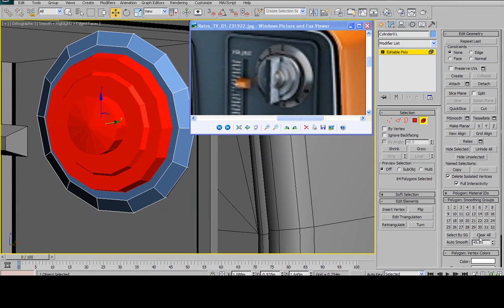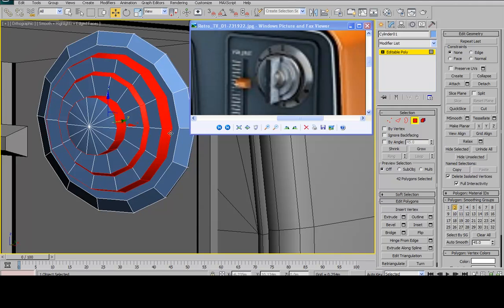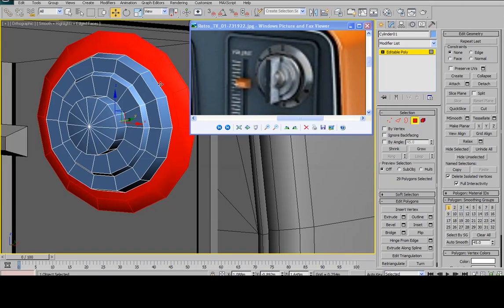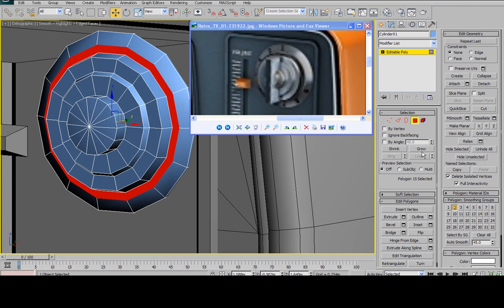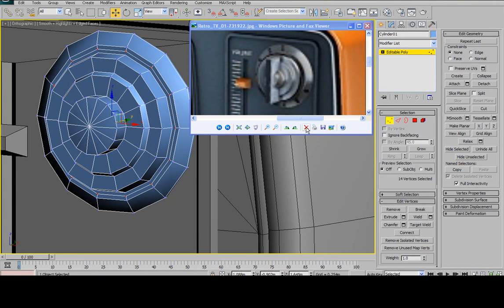Now I'll just set some smoothing groups here. I'll give everything a smoothing group of 1. And then I'll select my outer edges here. Ring, Control, Face Selection Mode, and set them to 2. And I'll do the same thing with this back bevel here. Clear all, set to 1. And then I'll take my top polygon here, and I'll set it to 2. And then just to make it nice and clean, I'm going to cap it off as well. So rather than extruding, I'll just inset, select the vertices, and then hit collapse.